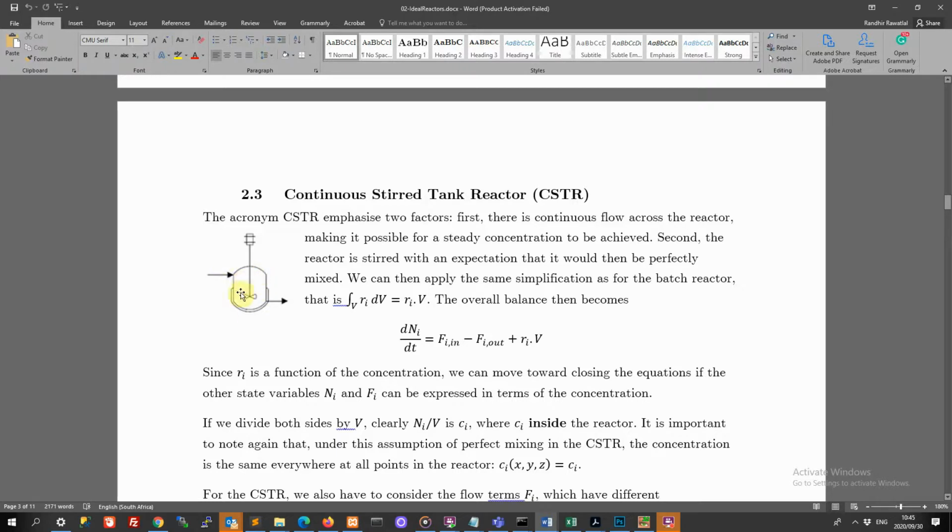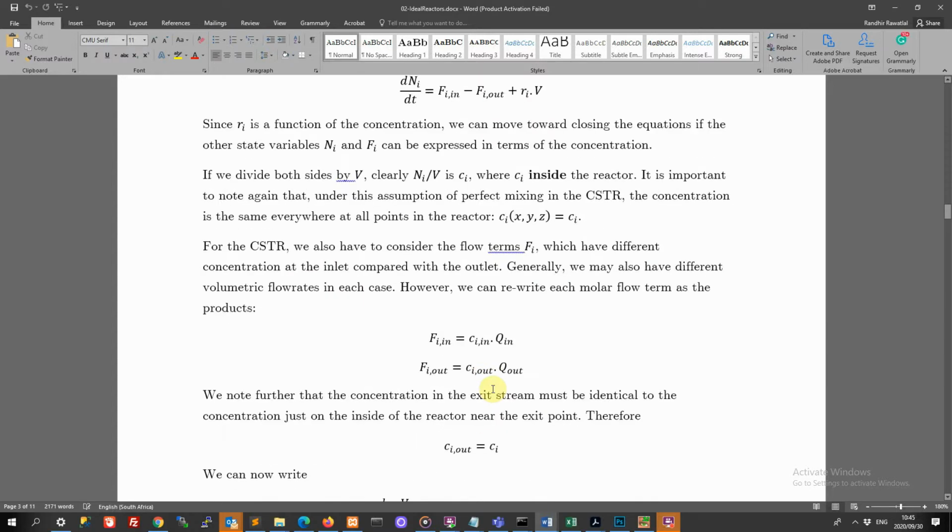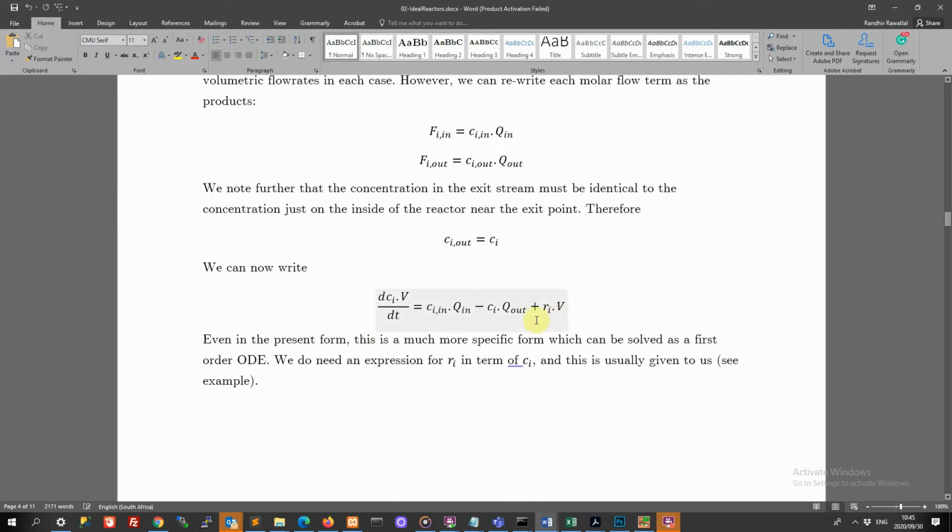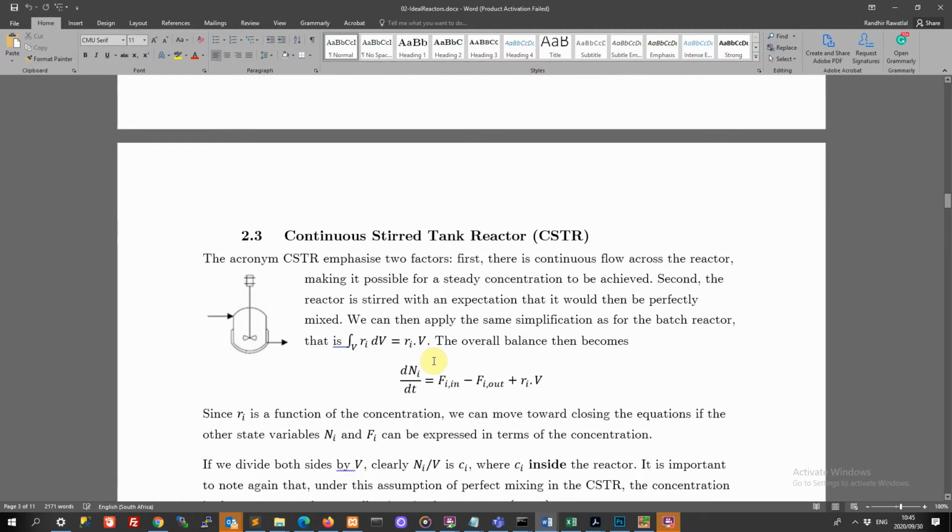So if your reaction is dropping the pressure, that means necessarily your flow rate out here is going to be lower than the flow rate in here, right? You can think of the reaction as sucking in some of the molecules coming through here. And so you will have a lower flow rate through here. And you see, automatically then that throws out everything we've done in terms of our material balance. Well, not quite. We'll look at how we can modify what we are doing to account for this pressure drop.